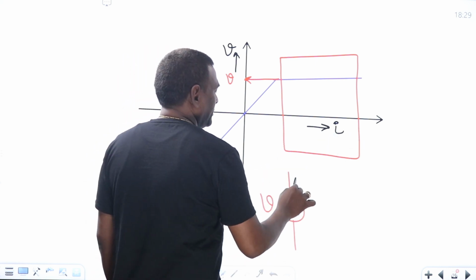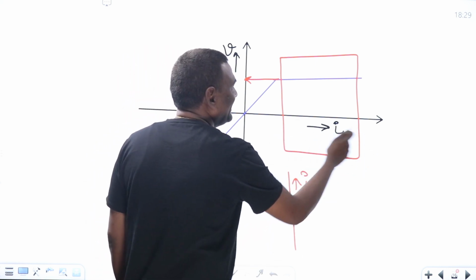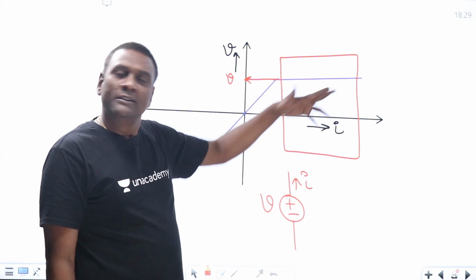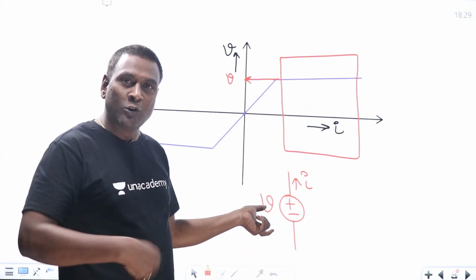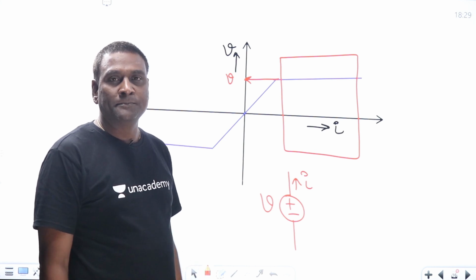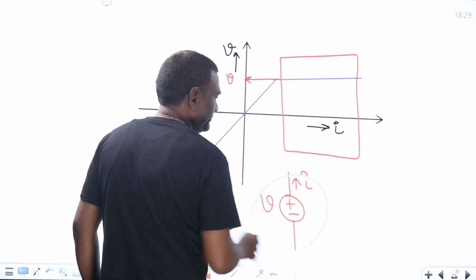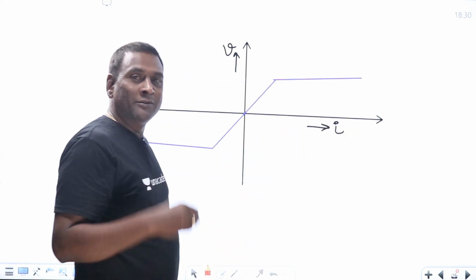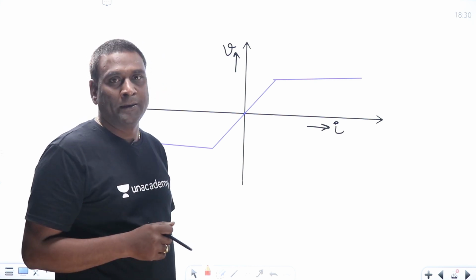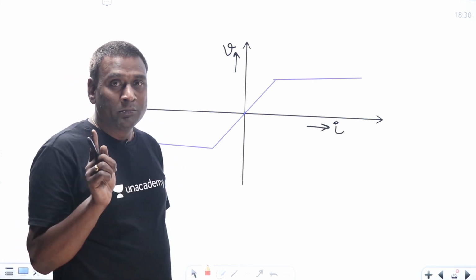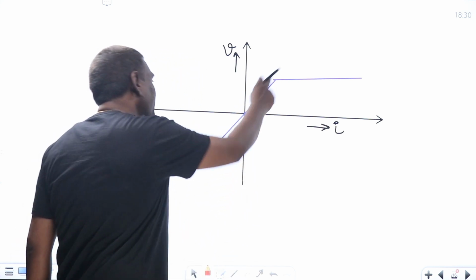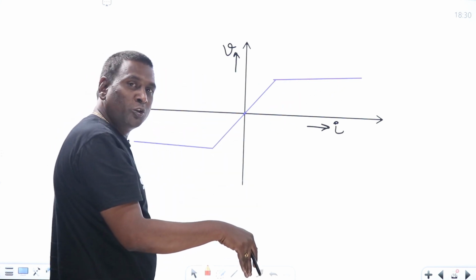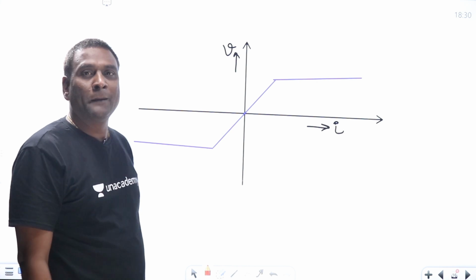Okay, current of this particular value. Because from here to here, current can vary, but voltage is going to be constant. So the moment you have zero slope, there is no other way. We have to model that way. Either voltage source or current source, depending on the thing here. Okay, so point here is simple. In this particular region, I have to model that with voltage source only. Okay, so here characteristic is there in the first and third quadrants only, but with zero slope it is going to be active. With negative slope it is going to be active. With positive slope it is going to be passive.